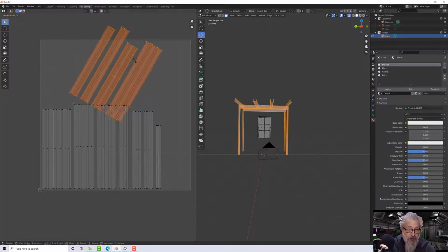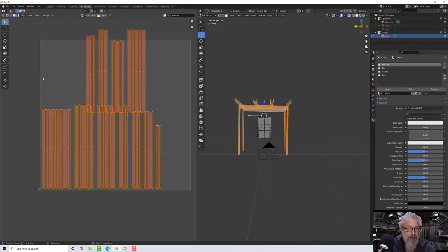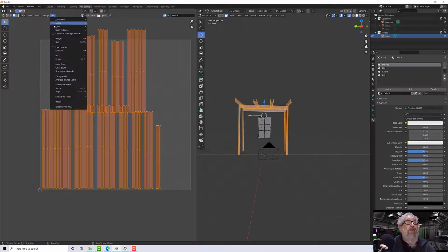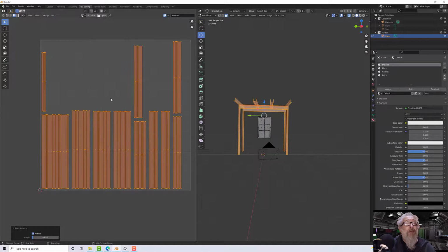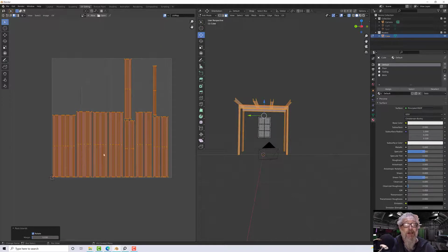If you hold down Control, it will start to snap, and just get it to vertical and then click, and then click off and A, and then we'll go to UV and pack again. There we go. Might now have a little bit too much in the way of margin on our packing here, so let's just take that down to 0.03. That will give us a little extra texture room to take advantage of.